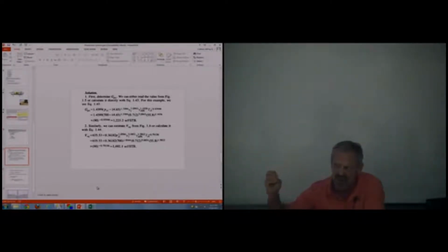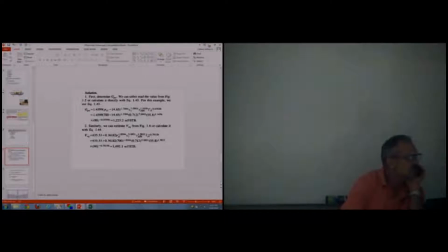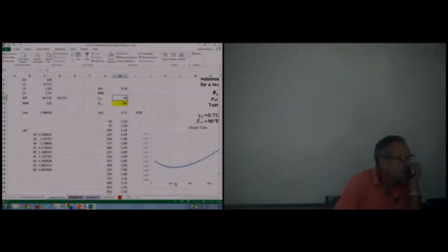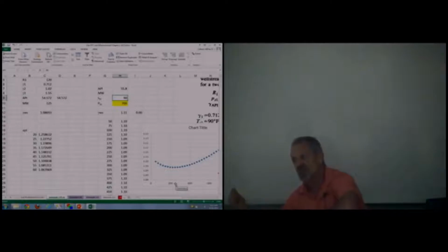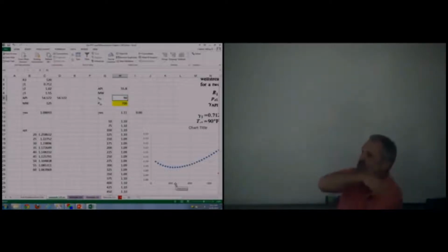Now, whether I can follow that logic, you know, I want to jump on that point first, but now let me try to jump on your logic. What you would want is the lowest gas gravity, because that means more of your middle components are over in the liquid, which would expand the amount of liquid you have. So you've got it right on. Yeah. These are the types of things.